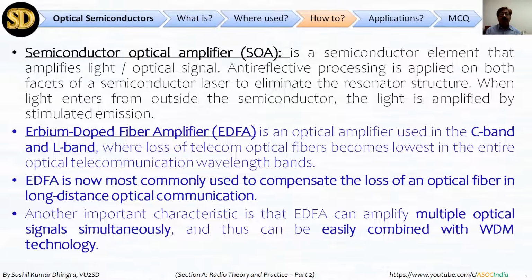Continue, because the examiner can ask questions on some other parameters. So I am explaining some terms. Semiconductor optical amplifier, SOA, is a semiconductor element that amplifies light or optical signals. An anti-reflective coating is applied on both facets of the semiconductor laser to eliminate the resonator structure. When light enters from outside the semiconductor, the light is amplified by stimulated emission. This is SOA. Same way EDFA, erbium doped fiber amplifier. This is also a kind of amplifier to amplify light.